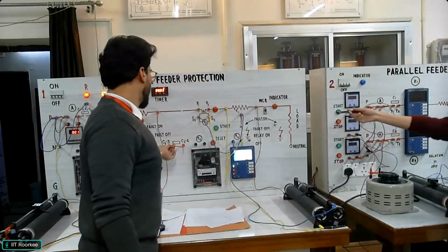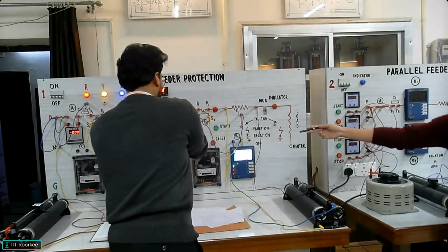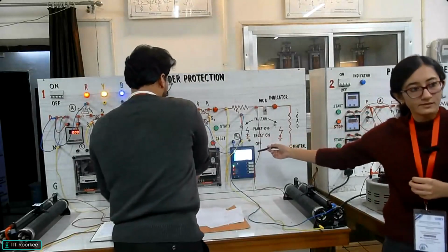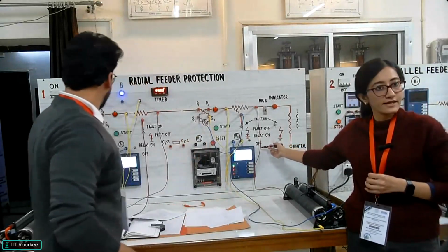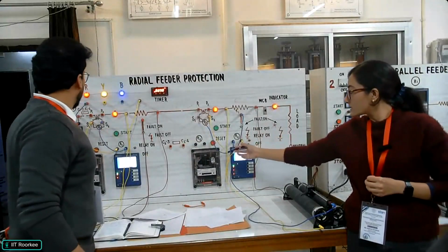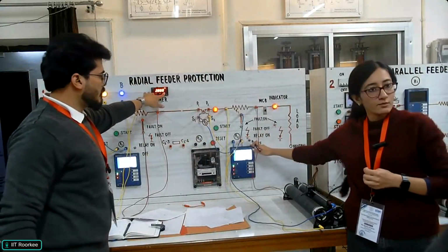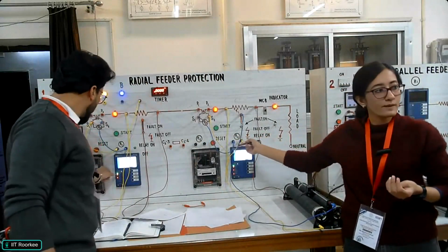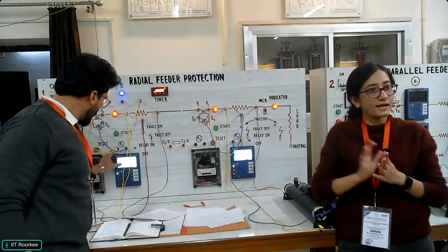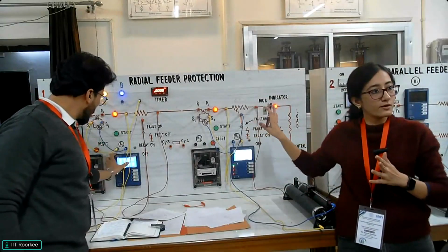Okay, so meanwhile he changes the connection, I'll explain. There you can observe two relays. One is the older generation electromechanical relay, and this is the new generation IED or digital relay. Obviously these are the most advantageous relays. Like with the previous batch, we just discussed that electromechanical relays are fine. They are robust and good for local control and local operation.